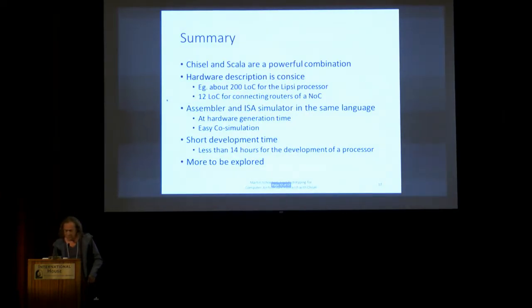Good. In summary, I think the combination of Chisel and Scala is a very powerful combination. Hardware description can be very concise. It's a small processor. Of course, small is just 200 lines of code. I've shown you 12 lines of code to connect the generic NoC. And having Scala at hand, you can do an assembler, you can do a simulator, a software simulator, and run this in co-simulation. And I've shown you, not in an afternoon, but I managed to do this in 14 hours. And more to be explored by myself.